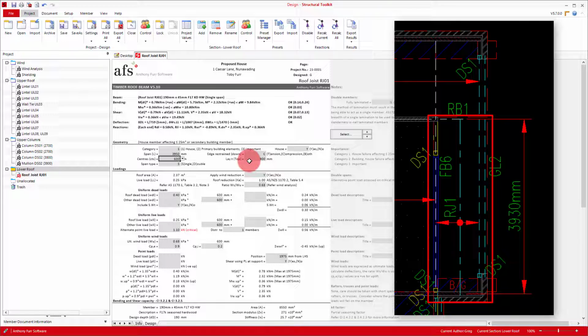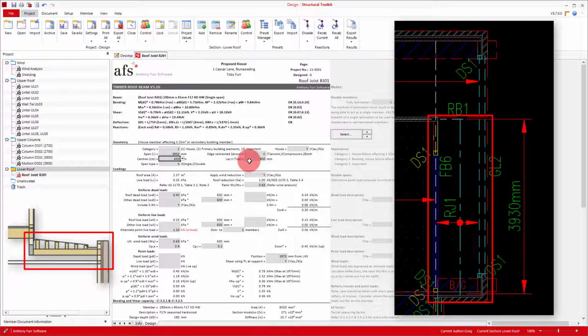Roof joists are typically spaced in the roof at either 900 centres for sheet roof or 600 centres for tiled roof. These aren't concrete values however, and so you can adjust the spacing as necessary to suit your design. A good case of this is where there isn't much depth within the roof to fit roof joists, and so you reduce the spacing in order to help reduce the member depth. That being said, wherever possible it's going to be better to stick to the standard spacings. As our roof will be sheeted, we'll use a spacing of 900.